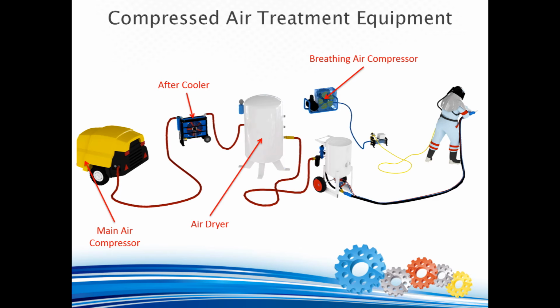Relative humidity is the percentage of water vapor in the atmosphere in relation to the amount required to completely saturate it at the same temperature. As air gets hotter, it expands and can hold more moisture. When air at 100% humidity is cooled by nature or man-made mechanical devices, the water vapor changes to small water droplets. In order to remove moisture from compressed air for blast cleaning, it has to be cooled by some means so drops of water can form and be removed.